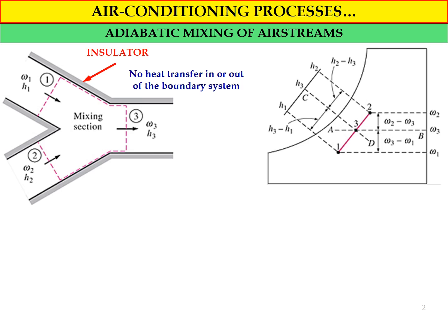Okay, from the figure we can see the enthalpy differences between state number 1, state number 2, and state number 3, and similarly the specific humidity differences: omega 2 minus omega 3, omega 3 minus omega 1. For the enthalpy we have H3 minus H1, H2 minus H3. So we can use this relationship of enthalpy and specific humidity to obtain the other parameters for the process.